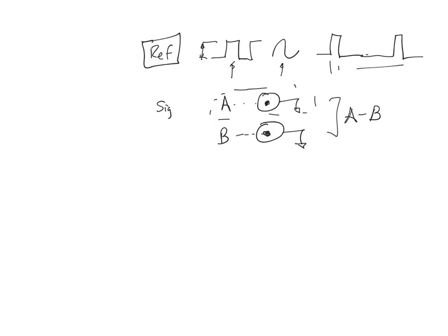On the signal area, you'll find the sensitivity setting. You just need to set that so it's reasonable for the signal that you're sending in. So it's such that you're not overloaded when the overload light comes on, but preferably such that it's close to the signal amplitude, so you're using the dynamic range of the lock-in well. In other words, the signal's not so small, not microvolts at the point where it's doing the multiplier.